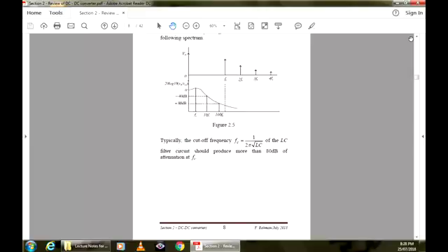and a ripple at that frequency, and then at twice Fs, the switching frequency, and so on. All right? That's what the output voltage waveform at the input of the LC components is. If you do a Bode diagram, it will look like this. L and C make a resonant circuit, so it will be a bit of a peaky Bode diagram. This is frequency and this is magnitude.